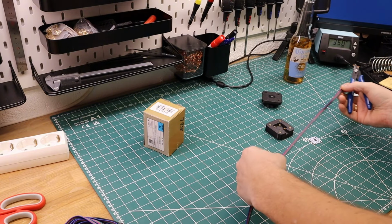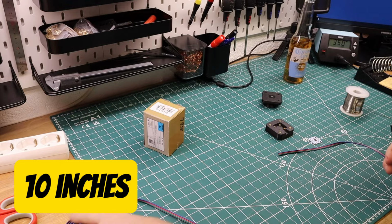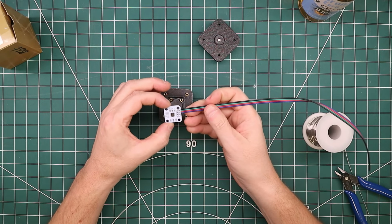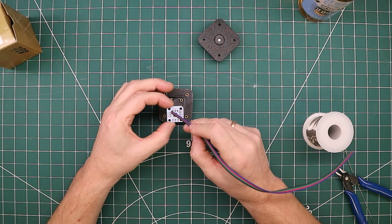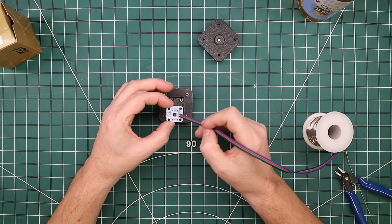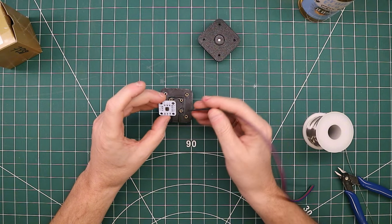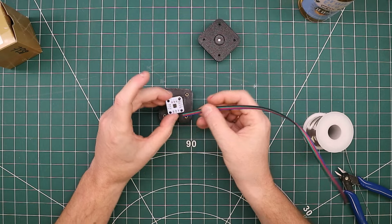Let's start with, yeah, a little more than 25 centimeters of cable. Should be enough. The interesting challenge here is that you only need 4 cables, but you need to connect it to 5 different places on the board here: VCC, ground, dir for direction, and clock and data for the I2C bus. So I will need to somehow attach one of these wires to both the direction pin and the ground pin.